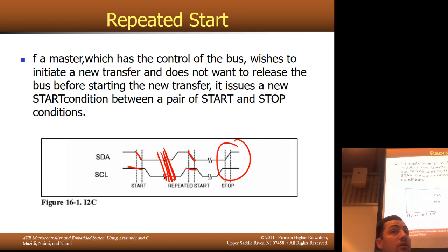It's not fair, okay? It's a quality of service issue. You can starve out everybody else on the bus just by doing this kind of move right here. But there's a reason, okay? If you need this data and you need it now, you can't get the first upper byte of a temperature in, say, a furnace, and then something else goes off and finds the weather out today, and then get the second byte. You need both bytes at once. Okay, so that's what's going on with a repeated start.